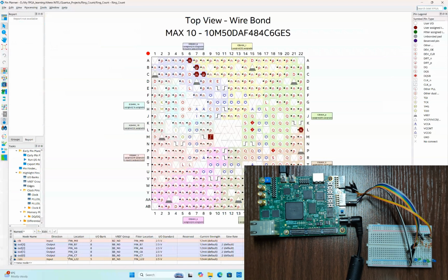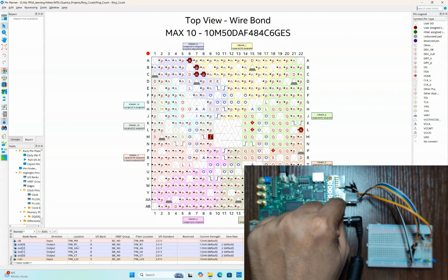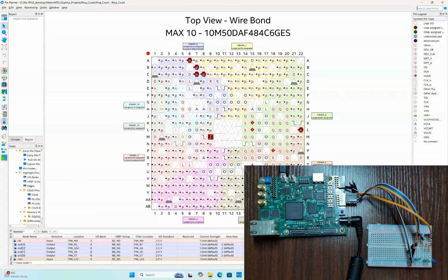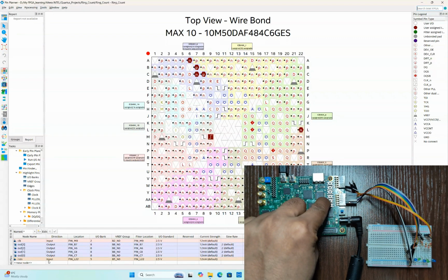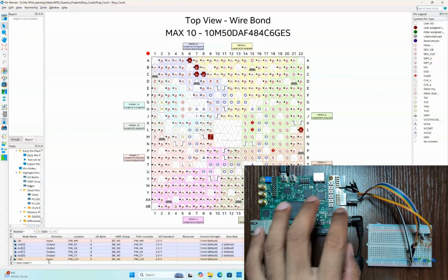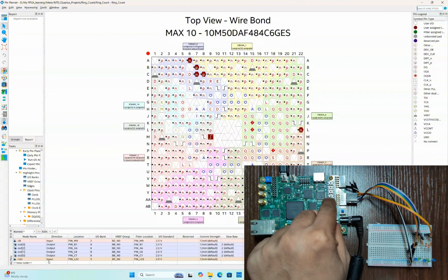we already connected the pins. So these four output pins are the pins for the PMOD connector, which is this connector. As I said, it has two PMOD connectors, so we are using the first connector here, and then we are using one reset switch, which is this switch. There are two applications of this switch. First of all, we have to press this switch when we start the code. Otherwise, the counter will not know where to start, and it will get stuck at some random value.